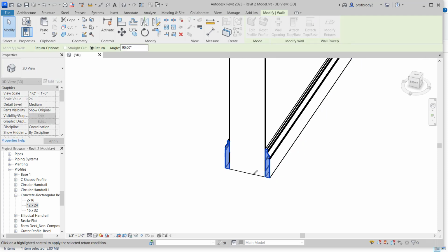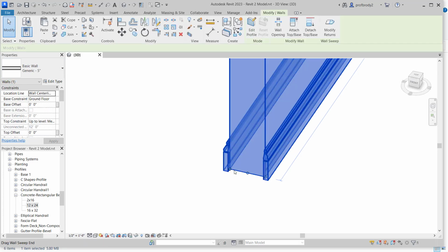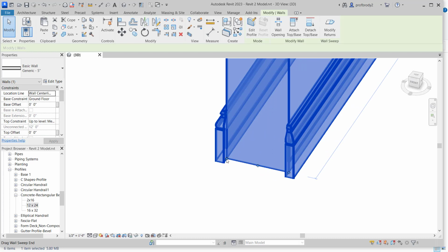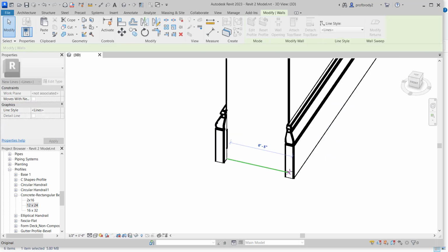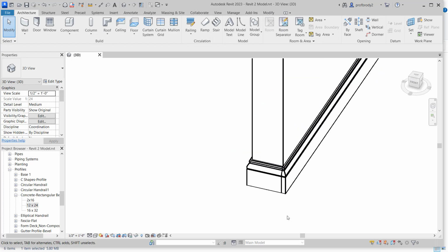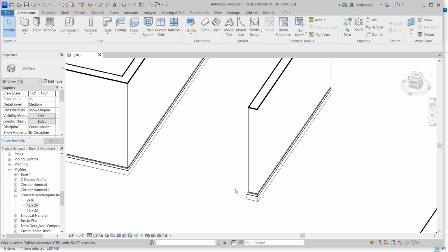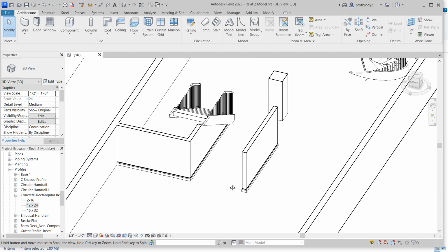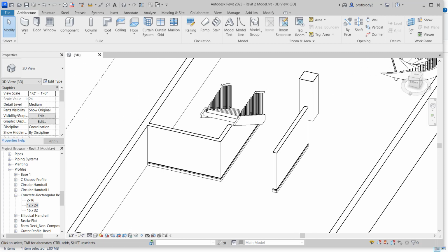You should be able to add a return over here just by clicking with this kind of, I don't know what you'd call it, pencil, knife? Not really sure. But now when you click on it, there's another grip available, and you can drag it all the way around to the other end. It does leave a little line there, but you'll see later on those will disappear. And of course, it's a pretty tiny detail in a pretty big project.